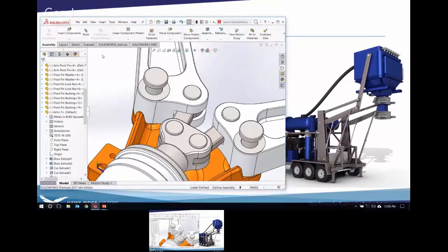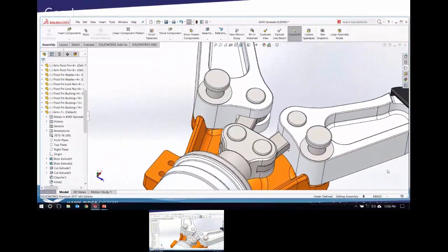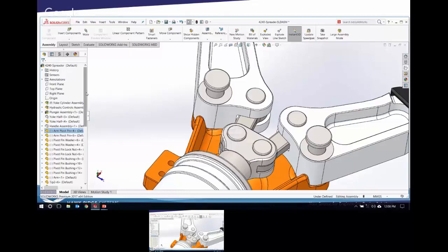Can you select an assembly in that dialog for these components? You can select assemblies or components. You have to be able to drive that component at the assembly level. So for instance, if I bring a gimbal into a larger assembly, can I move components of the gimbal at the higher level, or do I have to have access? You'd have to make that subassembly flexible in order to do that.